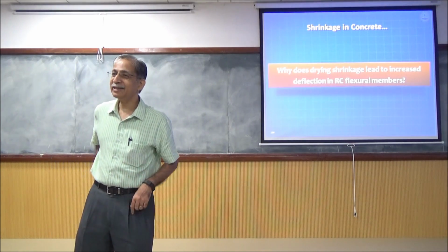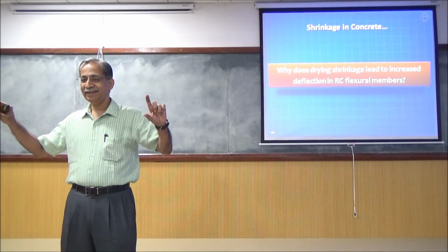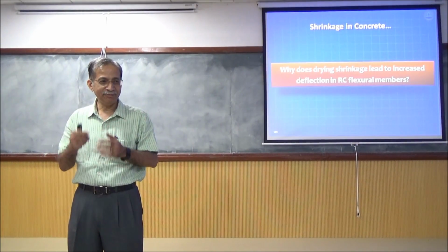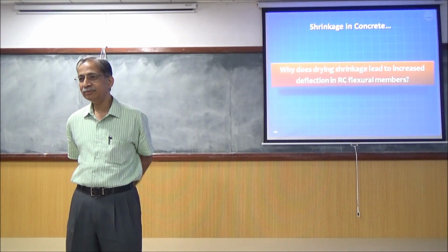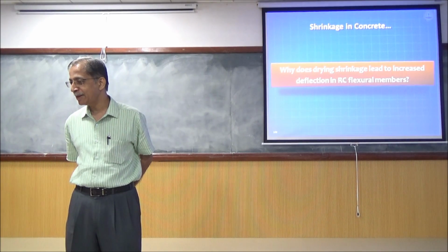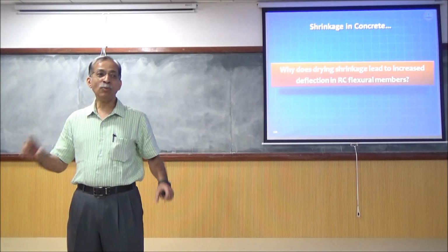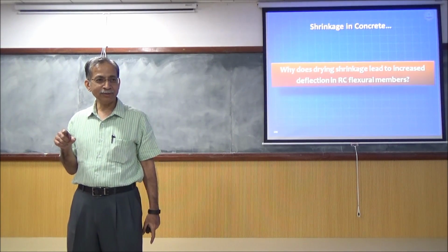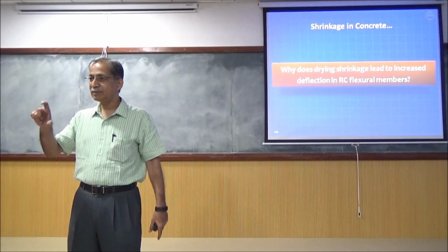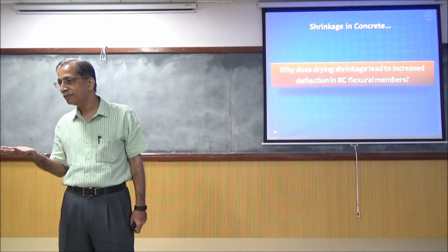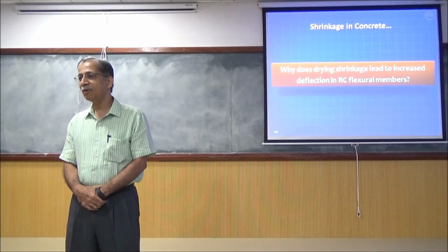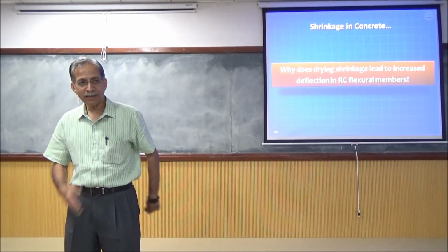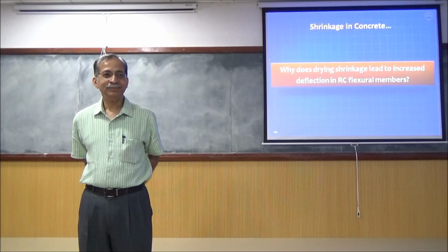Let me trouble you with a tricky question. Let's say I remove half the load from one half. Then will the deflection at midspan also become half? How many people agree with that? It would become 5 by 384 into WL raised to 4. Because I removed half the load, will the midspan deflection also become half? Yes or no? How many people say no? Why yes? Can you prove it? Superposition.